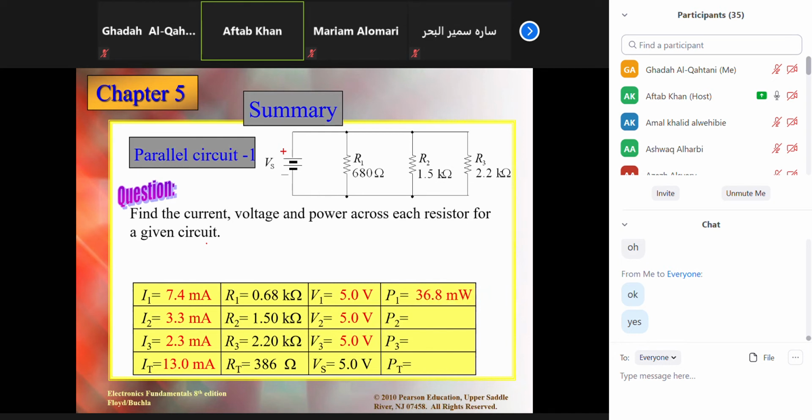All right. Now the power. So guys, for the power, the formula is the same as what you learned in the previous chapter. Either P is equal to V into I, or V square over R, or I square into R, whatever. The easiest one, if you look here, is the multiplication of voltage and current. Voltage is in volts and current is in milliamps.